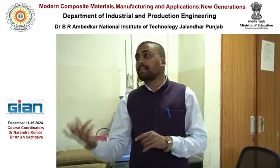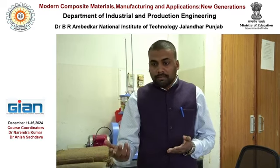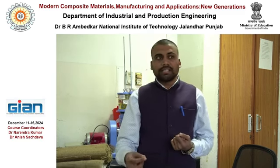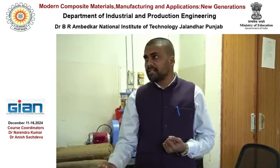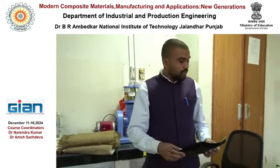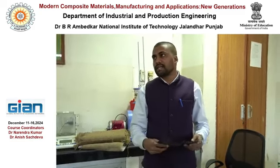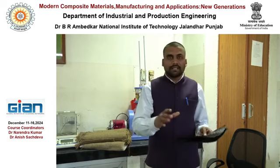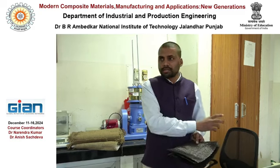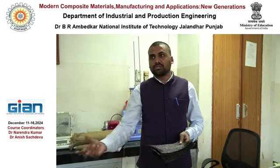But fabrics are of different types. For example, whether it is a woven fabric, or a randomly oriented glass mat, or a 3D fabric, right? So based on that also the void content will vary, even if you produce the composite with the vacuum bagging technique. But in comparison to other techniques, for example compression molding, you will get fewer voids with your vacuum bagging technique.